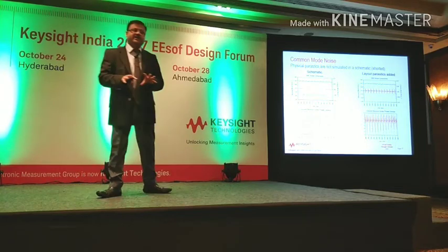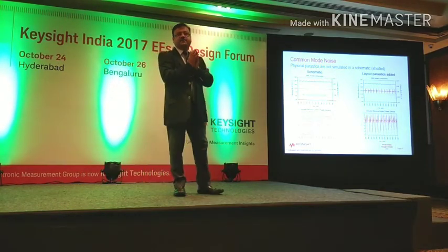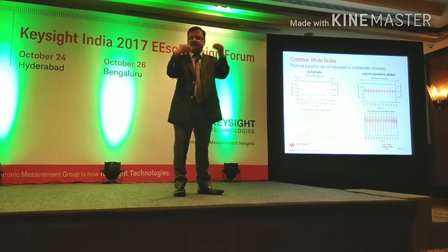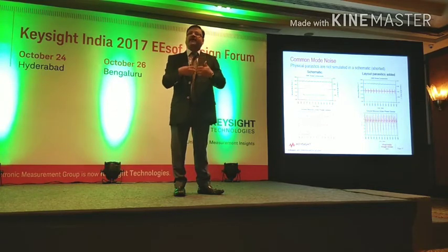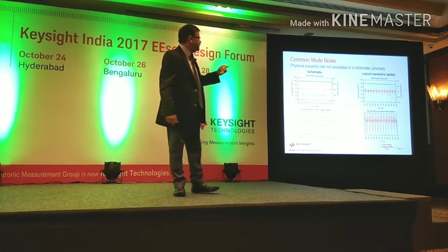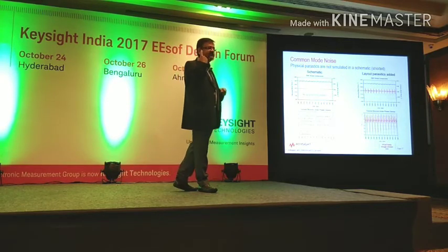So a lot of effects are coming into the picture. Size is one, efficiency is one. Within the same form factor, I was producing 400 watts. Can I do 800 watts? Because now your systems are getting complex. You have a lot more FPGAs, a lot more systems, right? So the demand for power is going up. System size is reducing. You're not expanding. So all these factors are driving up the switching frequencies.